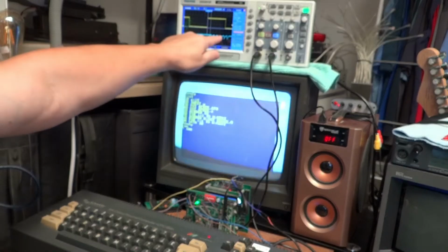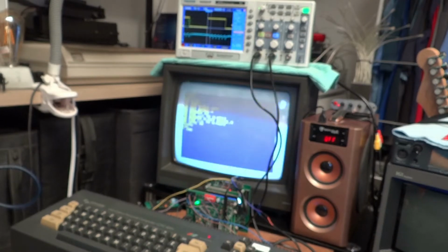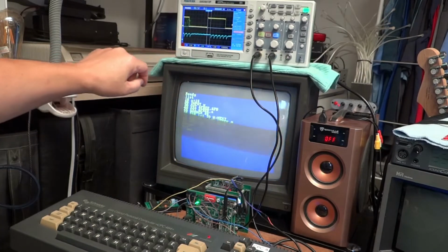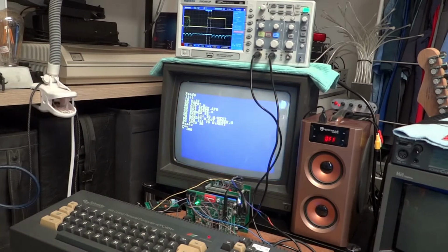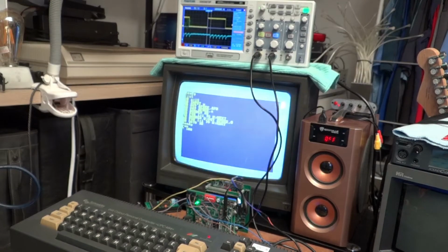At the bottom you see the signal from the photocell. And you can tell here, I'm using the start and end cursor, that on average the delay is about 25 milliseconds, where you see that dip in brightness. So it's between 20 and 30 milliseconds. On average it's like 25.